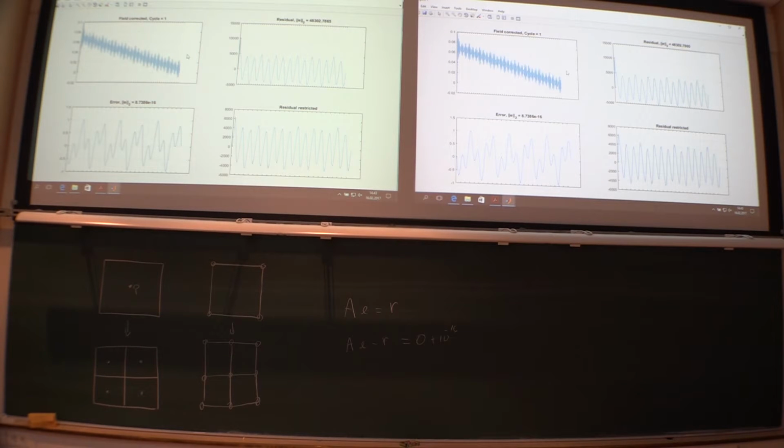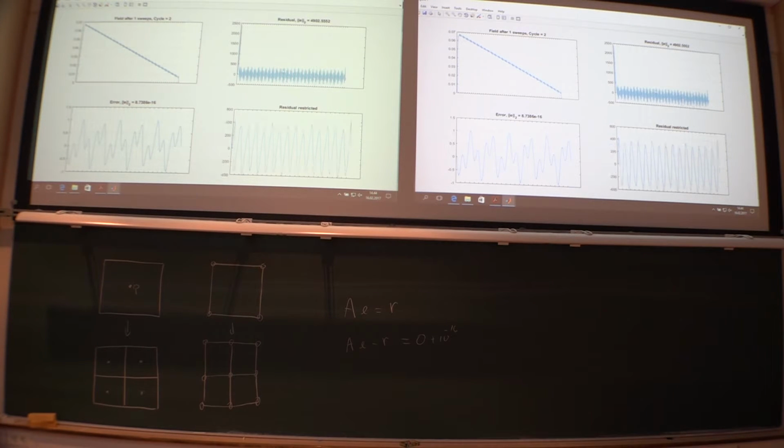Now this is the signal that we now have on the fine mesh, just rescaled, so it's only 10% here. And now it's very high frequency. So we do some iterations up here to smooth it down. Here actually only one iteration. That might be a little bit too few, because then we have the residual, which now is very high frequency. It can be very hard now to represent that signal down here on the coarse mesh. So this is maybe not ideal, but let's see what happens.